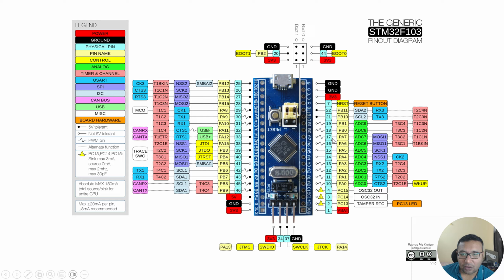Now quickly taking a look at these pins, you can see we do have a number of different general purpose input output port pins. Ground connection, 3.3 volt, reset connection, 5 volt, ground, 3.3 volt. This board can be powered using this USB or by directly connecting 5 volt onto this pin. Now if we look at this closely, you will see it has 2 LEDs, one connected as power on indication, another one is PC13. That's the typical user LED. That's what we're going to blink when we download our first program into it.